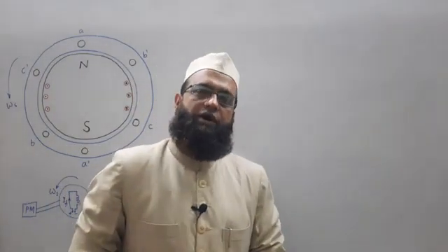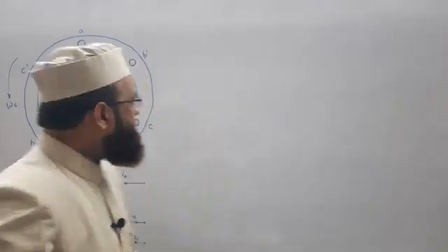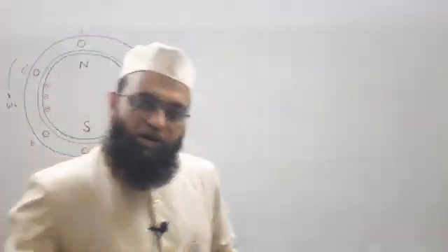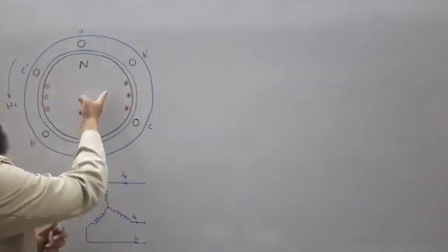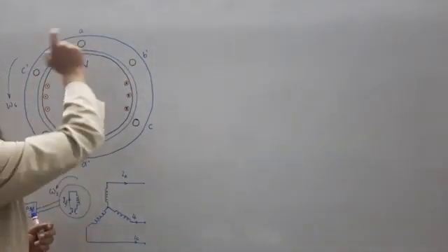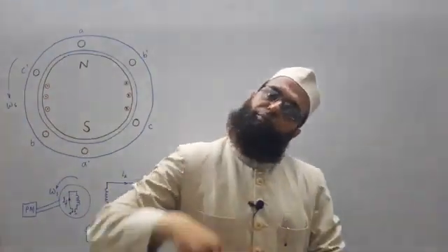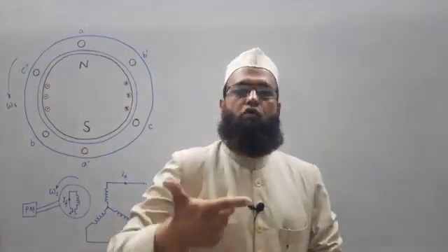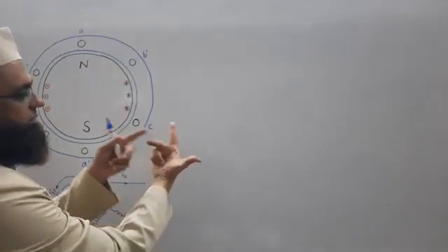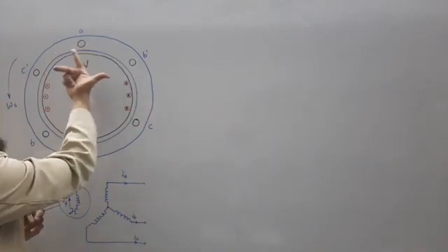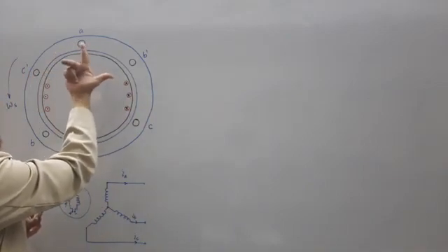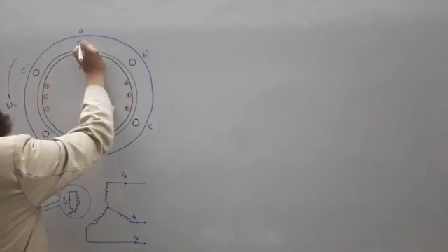In a simple way, we can check the motion of the conductor. The conductor is stationary, but it has motion with respect to the field. So if the field is rotating anti-clockwise, the motion of the conductor with respect to the field will be clockwise. So F is like this and B is upward; the motion of the conductor with respect to the field is clockwise, this way. So this is out of the plane, that is, a dot will be denoted here. This is the polarity.